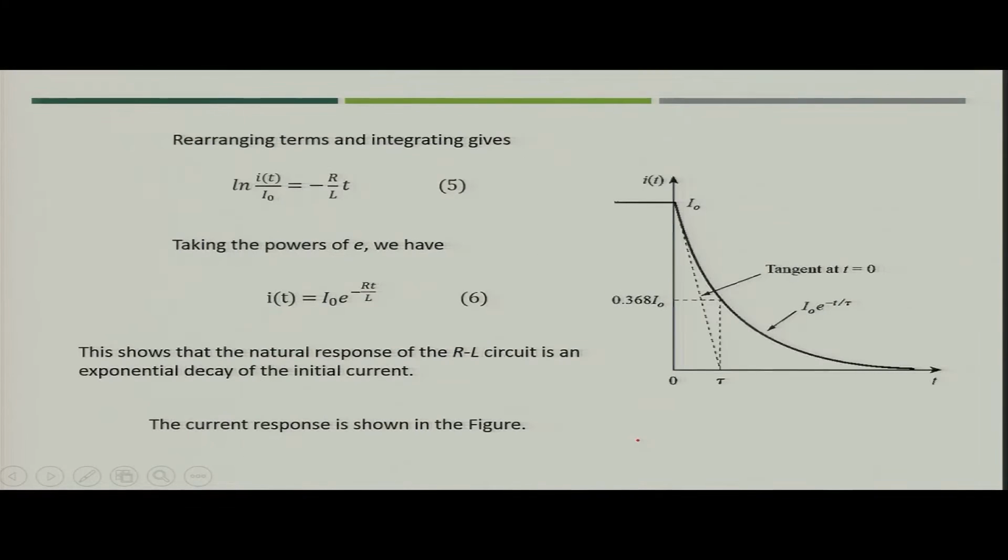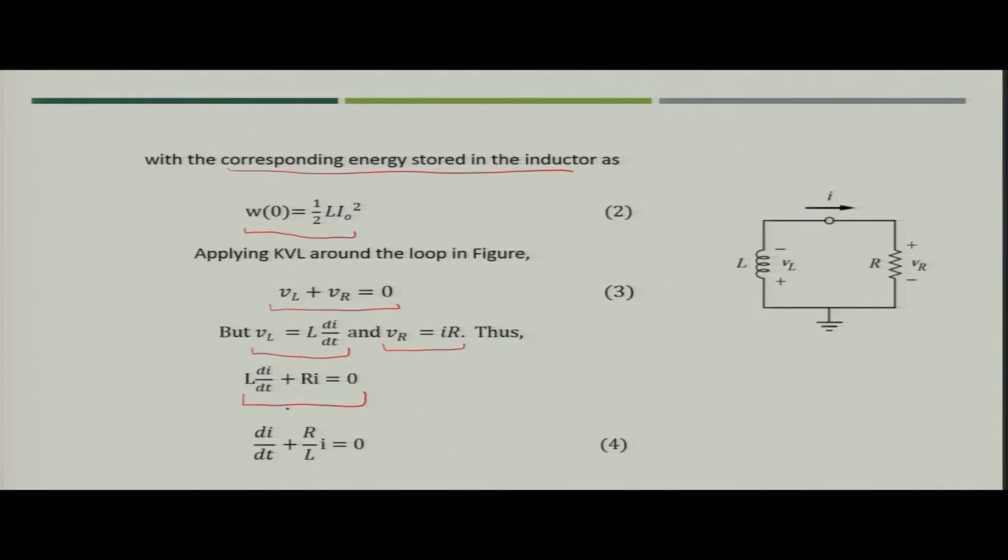Now, when you see this equation, you can use the integration technique to solve it as we did in the case of the RC circuit. We can rearrange this equation as di divided by i equals minus R by L into dt.